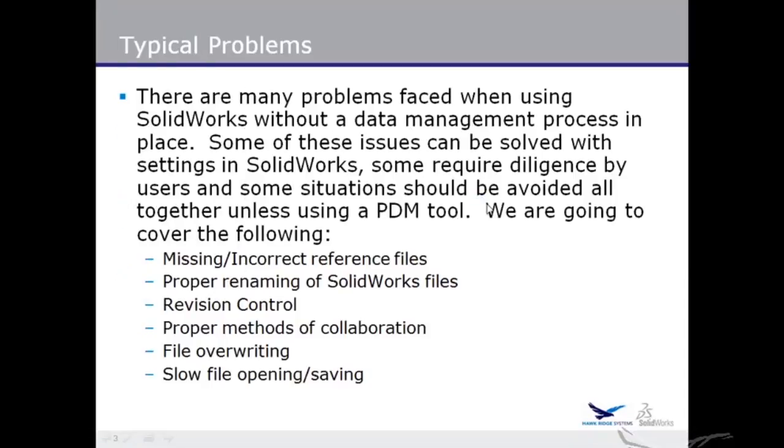And the first thing I want to talk about is the typical problems that you're going to run into when you have SolidWorks but you don't have a data management tool. And probably something everybody has run into is that you've got missing and or incorrect reference files. So you open up the SolidWorks assembly, you open up a drawing, and it tells you that it can't find the file, or it needs you to browse for a file or something like that.